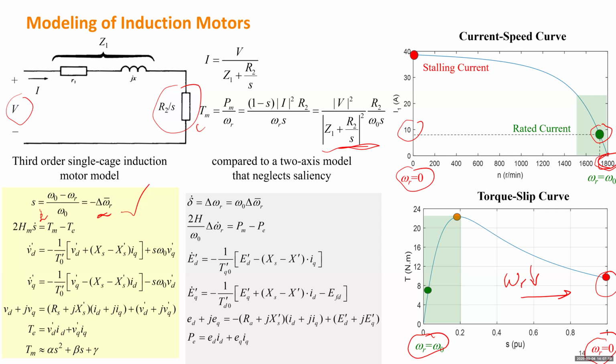So lastly, for the cylinder generator, the mechanical power is controlled by the turbine. So this mechanical power or mechanical torque is controlled by the turbine or governor, and usually can be considered constant in transient stability study. But in a motor, that torque will change with the slip following this function. It's not constant, so usually it can be simplified by some polynomial function. Definitely you can use other nonlinear functions to simplify the power, but basically that just represents what happens near the operating point.